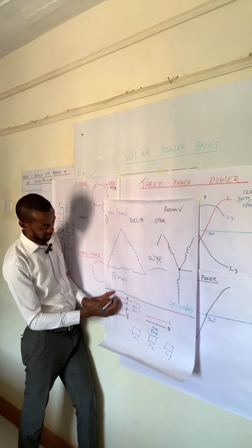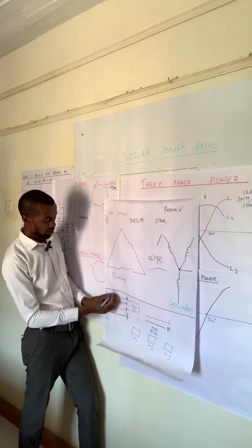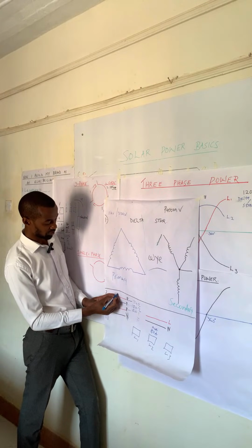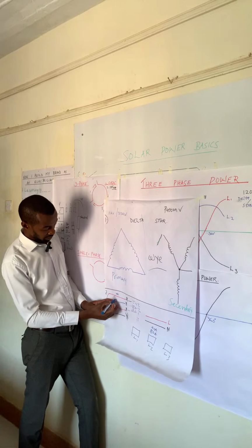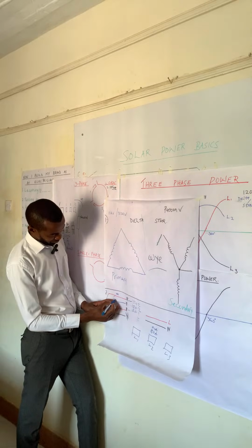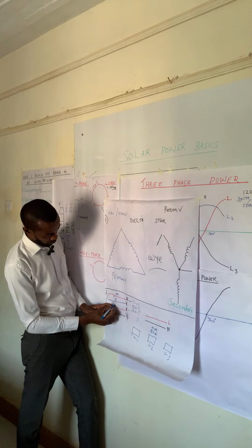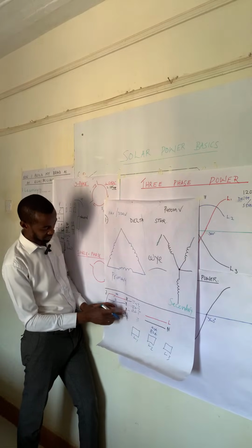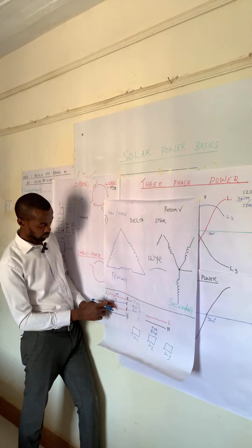Right? So what they need to do is to have a system whereby they can tell that we have connected several customers. In technical terms, we have connected several loads. We have connected 100 houses to red phase, and yellow phase has 70 customers. But on blue phase, we have 120. It means that that phase will usually have issues because that one is an overload.